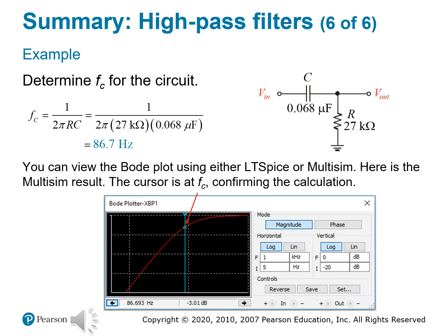A good point for lab is you might not be able to get your cursor right at that 3 dB. Just get as close as you can in the lab. But again, that's close enough for us to be on target, and close enough to confirm by practice the theory that we've been learning.